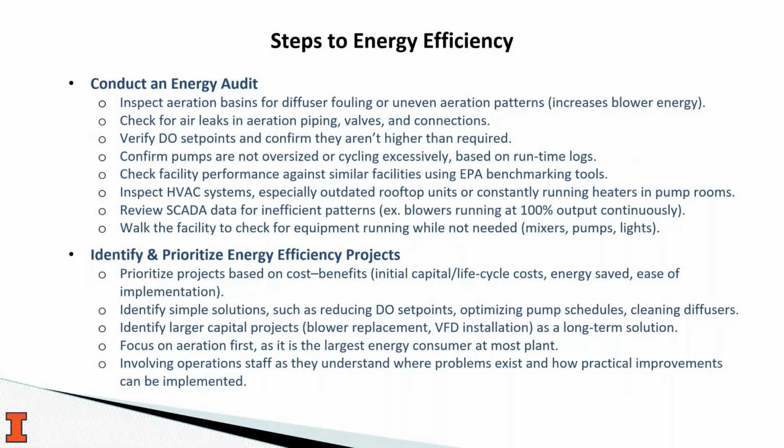It's always essential to involve your O&M staff or operations staff within this energy efficiency, energy benchmarking or energy auditing process, because they're the ones that really know the system. They usually are working with that equipment day to day. They probably know where they might be hearing some air leaks or some unexpected vibrations within certain equipment that might help you identify areas to improve first.